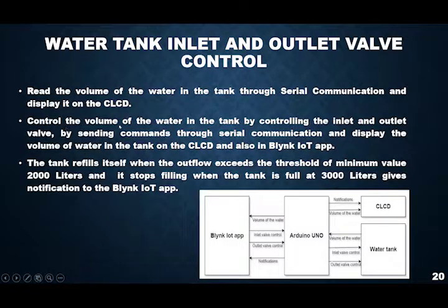So this controls the volume of water in the water tank by controlling the inlet and outlet valve by sending commands through serial communication, and displays the volume of water in the tank on the LCD and also in the Blynk IoT app. The tank refills itself when the volume falls below the minimum threshold of 2000 liters, and it stops filling when the tank is full at 3000 liters, and gives a notification to the Blynk IoT app.